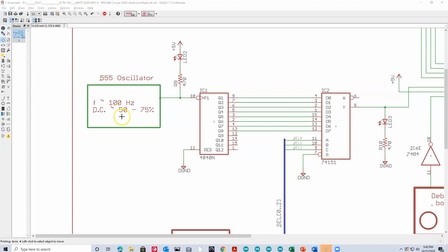The 555 oscillator is that little board that we're using, and I went over the details on how that works last week in the video. The LED here is simply a way to make sure that the output is working, even though there's a little LED that flashes on the board. Now, one thing of note: on that board there's a little black and red switch, and you're going to need to use that from time to time in this lab to turn the output on and off. So just be aware that that's on there.